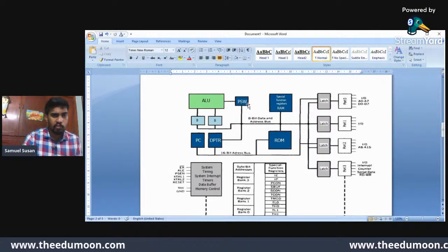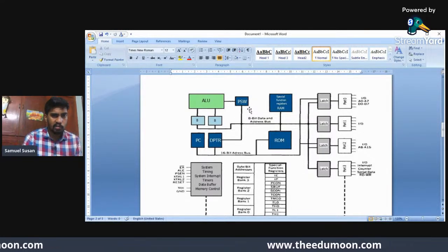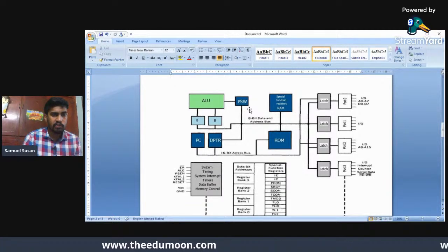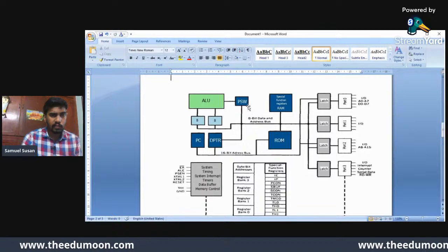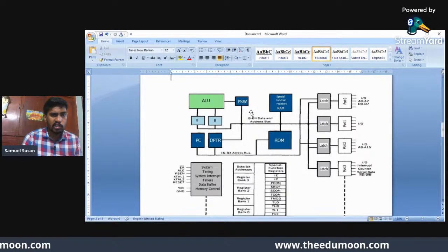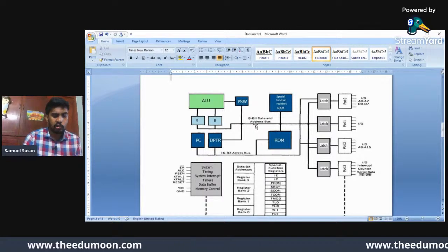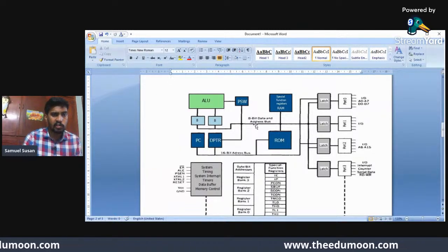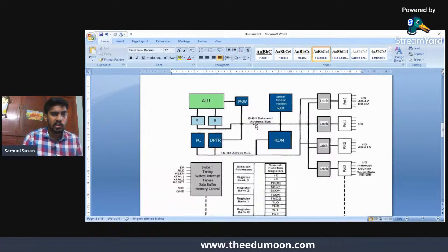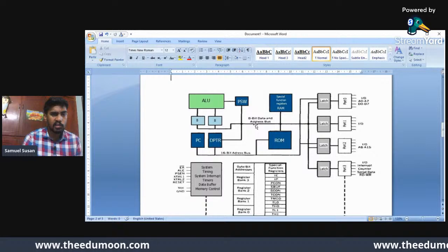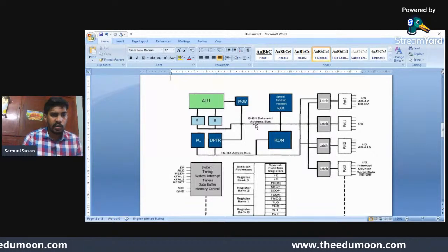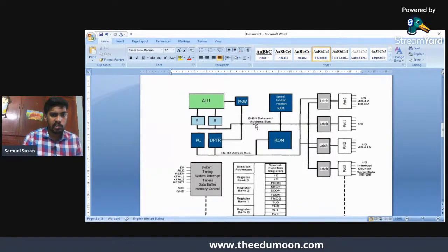Now PSW is one more important thing, which is a frequently asked question. PSW stands for program status word. The program status word contains flags like zero flag, sign flag, parity flag, carry flag, etc. So we know how they are actually used, the importance of flags. So generally, even if it is asked to explain PSW or a flag register, you can go with this answer. You explain each register, and from the syllabus, again we'll go back to the syllabus.